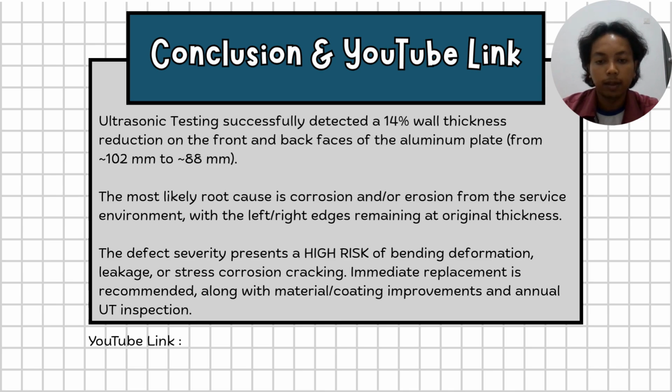The defect severity represents a high risk of bending deformation, leakage, or stress corrosion cracking. Immediate replacement is recommended along with material or coating improvement and an annual UT inspection.